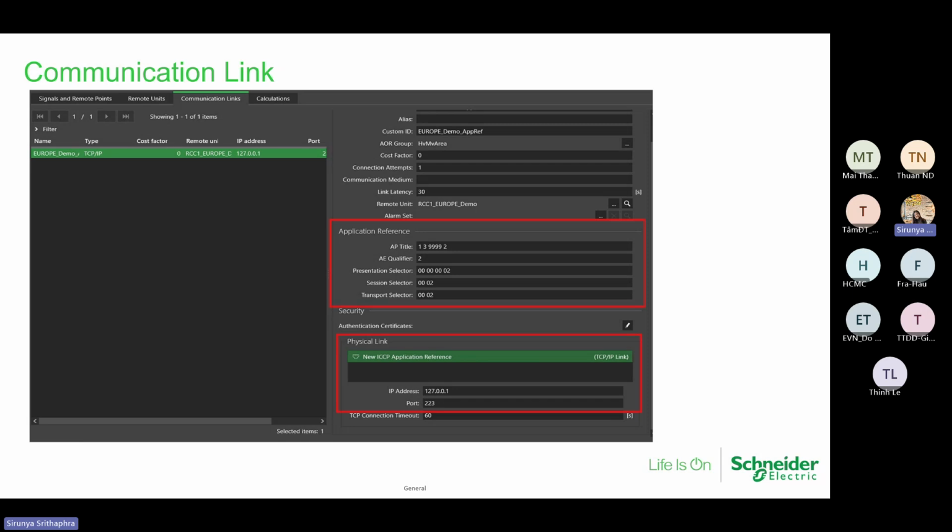We're going to, because we have an existing ADMS, create the ICCP link to export those signals from ADMS, like substation signals, and maybe we can combine them with the data from devices also, and put all those signals into one link, ICCP protocol, and send to the system. Okay. And for IEC 104, maybe we just connect to the DERs and maybe the microgrid.